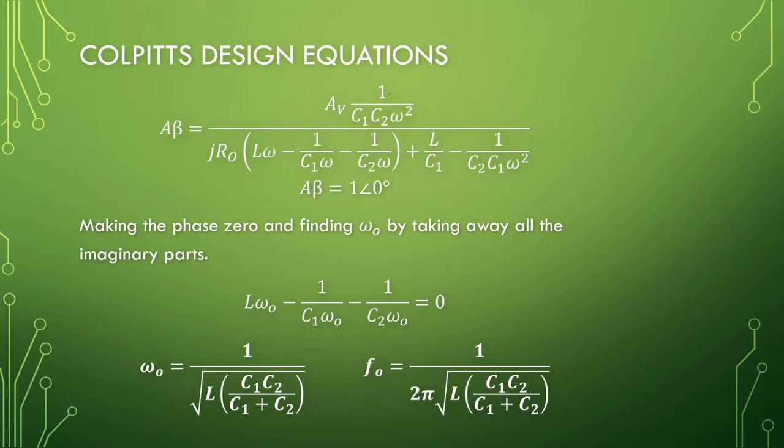And it will reduce to what we see here. So all our concerns of imaginary terms is here with our unknown output impedance of our amplifier. So the goal is to have all our imaginary terms be 0, right? So that will be our oscillation frequency.